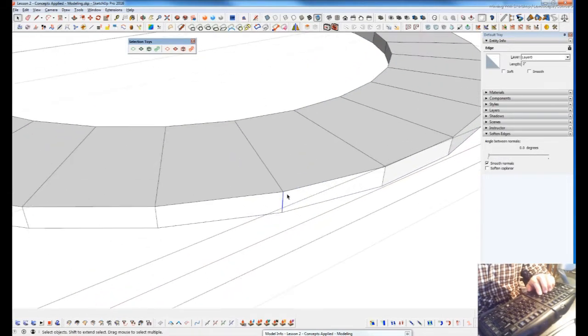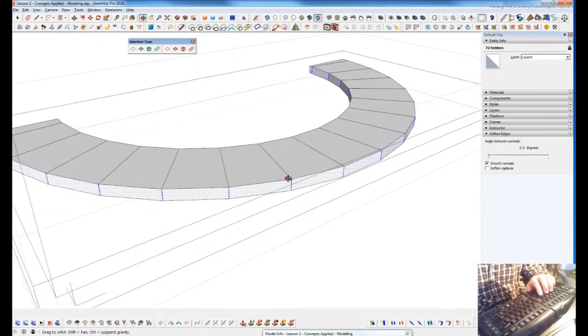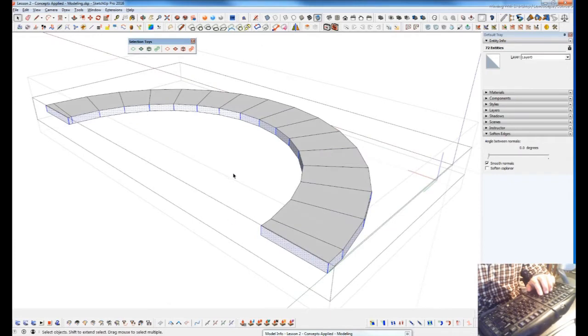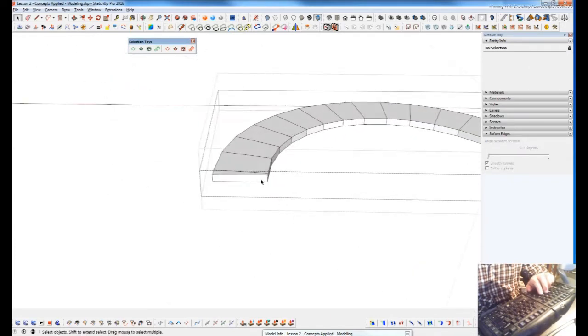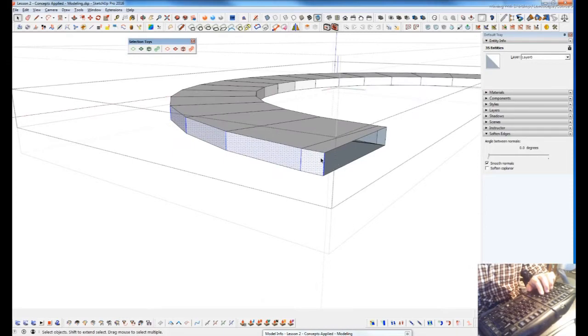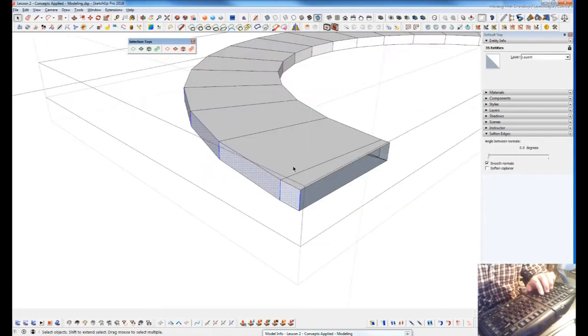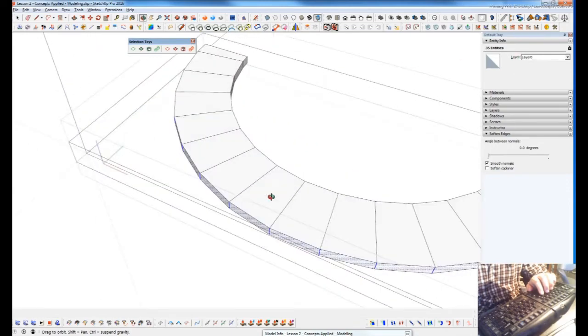But this will select the edge and the face in between all the way around. And if I didn't want it to select all the way around, then all I would have to do is say delete, delete, and now grab an edge and run quad face selection, and it'll stop right there because it ran out of quad faces to select. That makes sense.